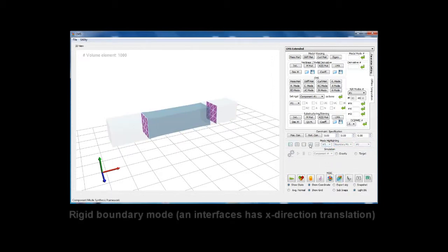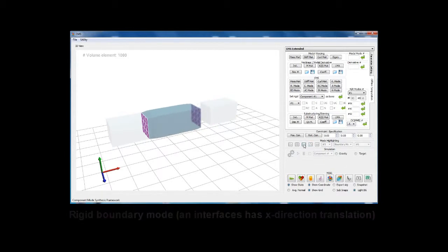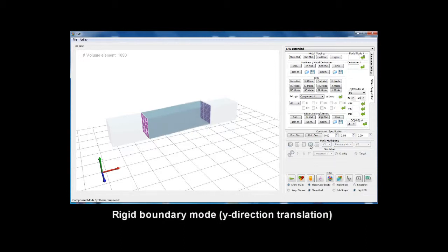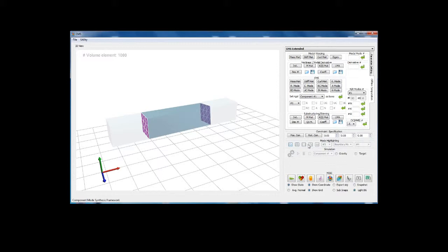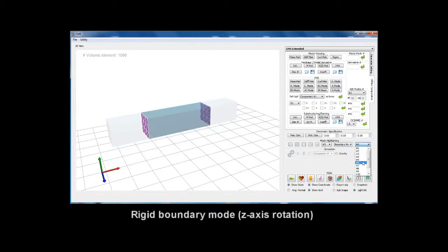We generalize the boundary displacement geometrically and minimize the system's potential energy within the boundary constraint. This can be done by solving the static equilibrium. The rigid boundary modes take advantage of the linearity of infinitesimal rigid body motion and construct the corresponding linear subspace with small size.